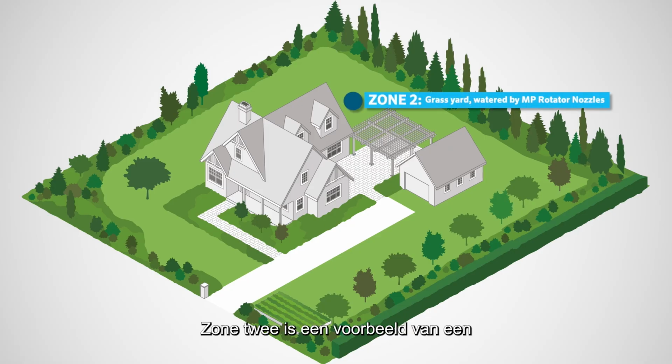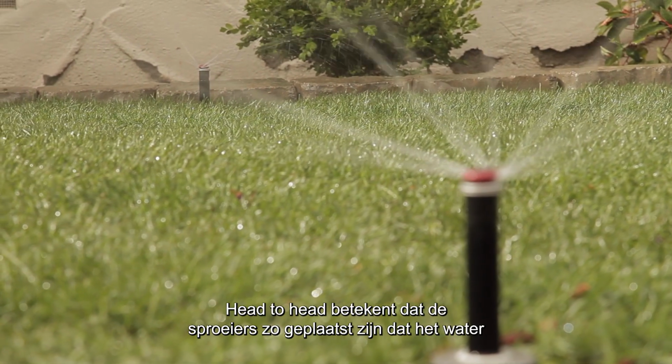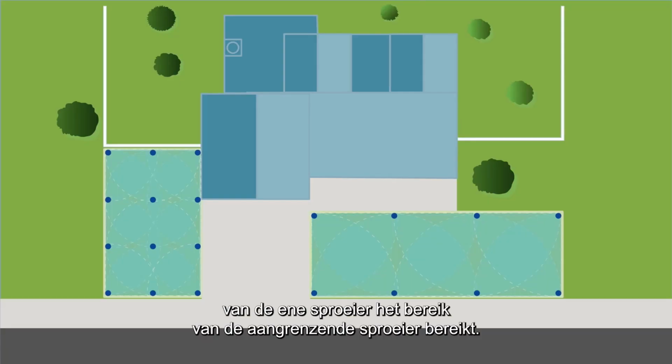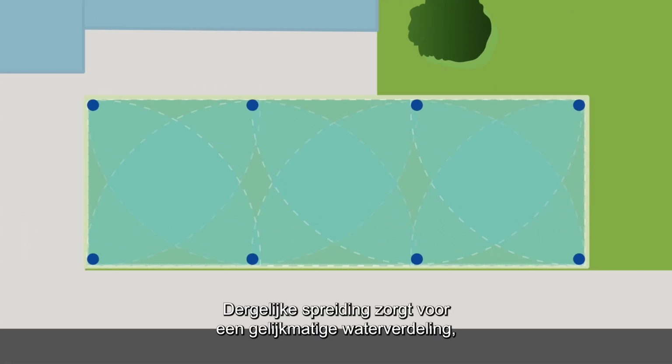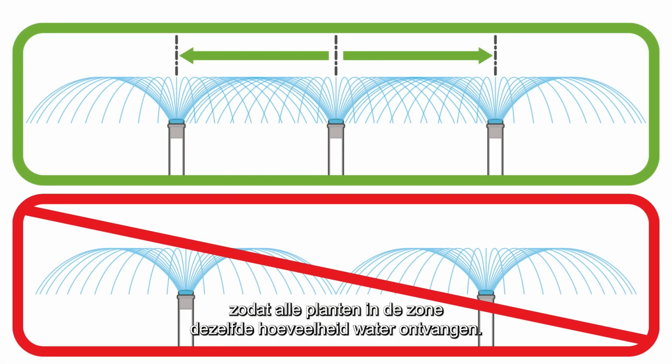Station 2 is an example of an MP rotator zone with head-to-head coverage. Head-to-head means that the heads are spaced so that one head's water throw reaches the adjacent head. Head-to-head spacing results in even coverage of water so that all plant material in the zone receives the same amount of water.